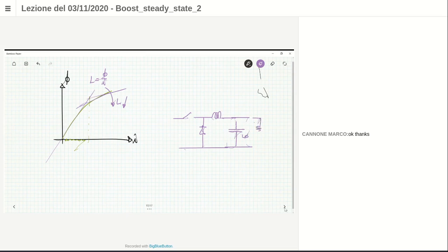Your output voltage is 0, so the voltage across the capacitor is null, so it acts like a short circuit dynamically for that short time interval in which it is increasing. You have a very large current flowing in this circuit. So you have inrush current, but you also have a switch which is in series with the flow of the current.